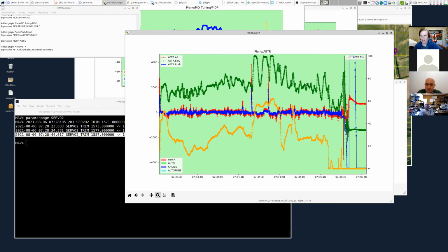And that is particularly important for landing at low speed, where you sort of run out of elevator travel when you're really nose heavy. The reason I caution about immediately jumping to nose heavy is that it's possible it's not nose heavy and the elevator just hasn't been mechanically adjusted, in which case moving the center of gravity back could cause a bad situation.